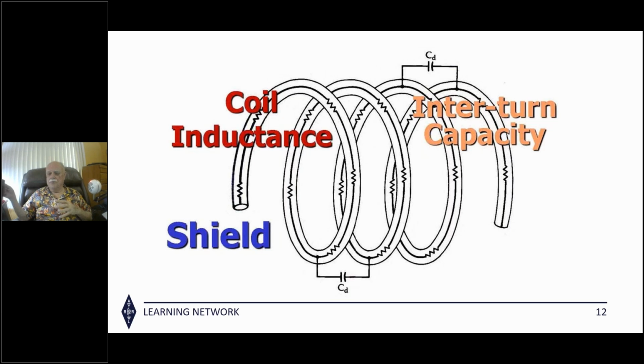And our final question for tonight, what is the difference between voltage and current baluns? That's a big question, requiring quite a lot of theory and lecturing. Fundamentally, the voltage balun is a transformer, and the current balun is the choke balun, which is just blocking shield current. The voltage balun is one that uses the phasing of its coils to choke off the current. That's as simple an answer as I can give quickly. It's a big study.